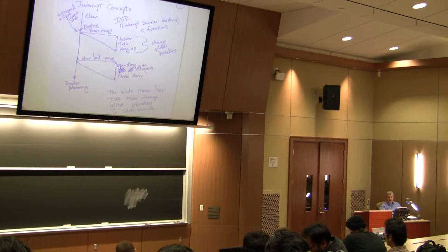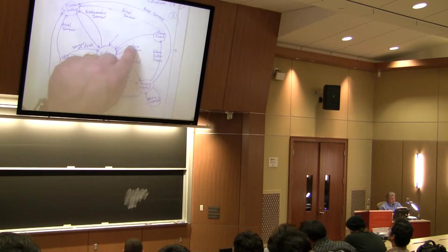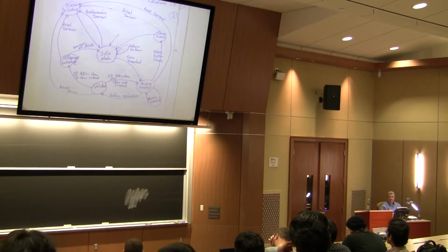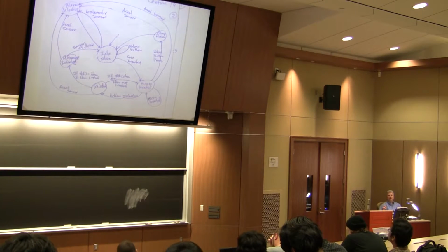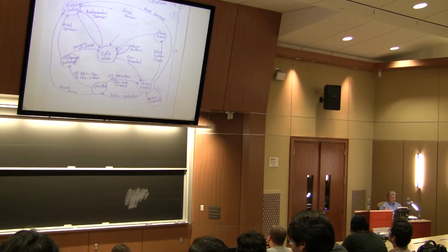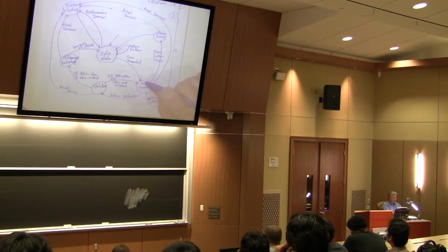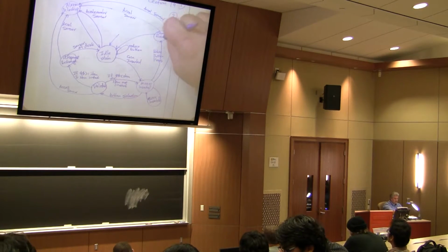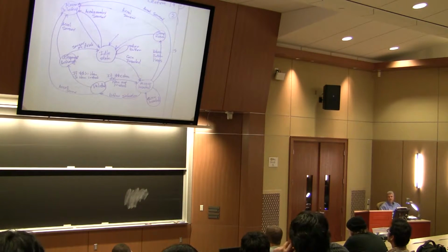And maybe something like pushing the return button will actually go to an interrupt service routine where you'll say, if your current state is money inserted, then change to the change return state, else just exit, right?